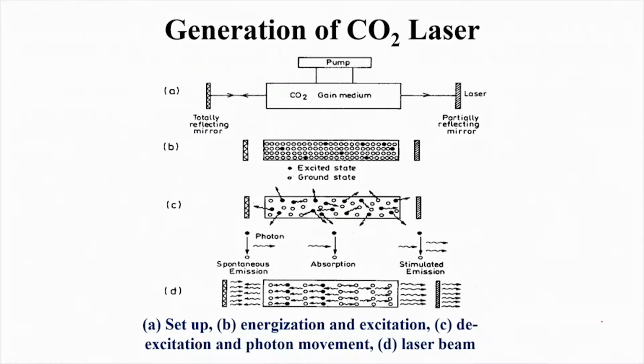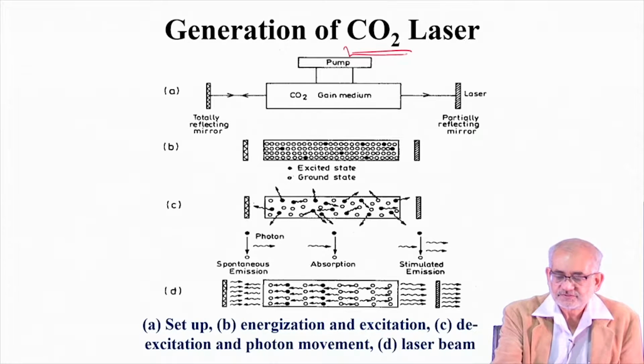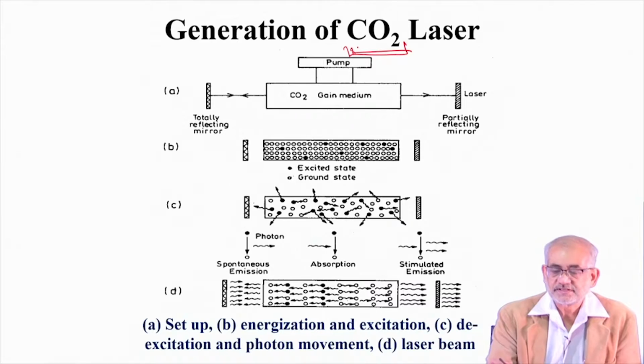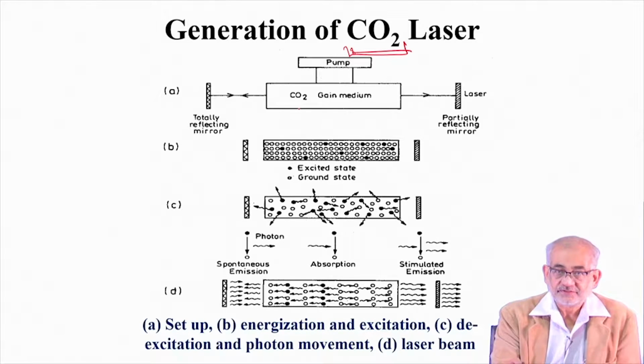So just a minute on the generation of laser. In this case, we are talking about CO2 laser. This was one of the foremost types of high power laser that was useful for material processing. So essentially you have a medium filled with various carrier gases, and a part of that, the active species of that will be CO2, of very low volume fraction though.